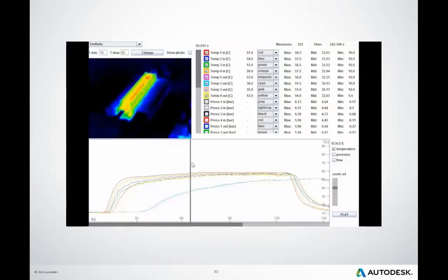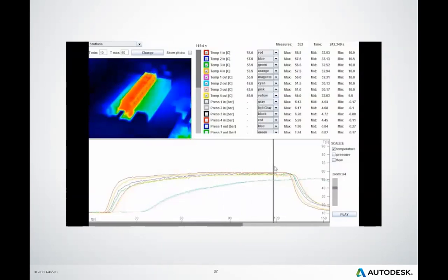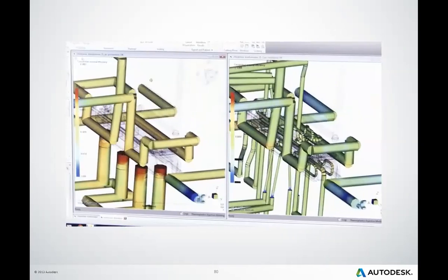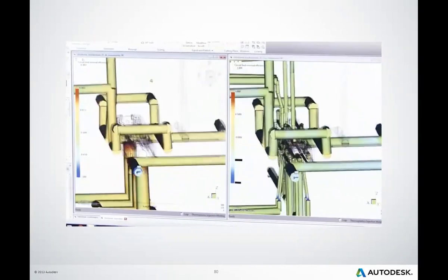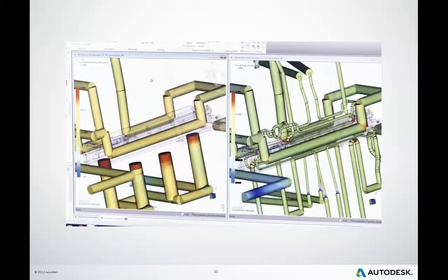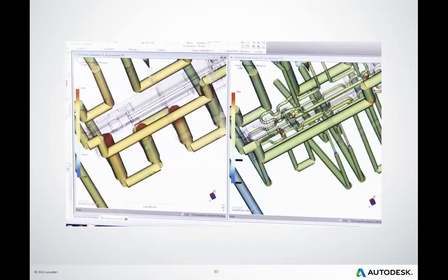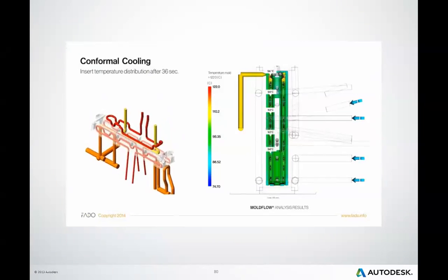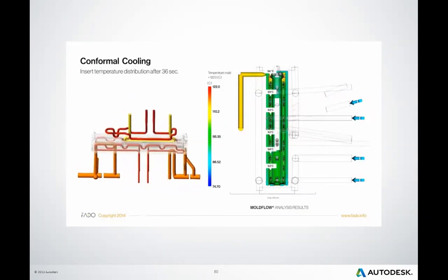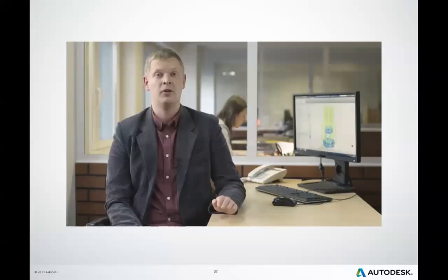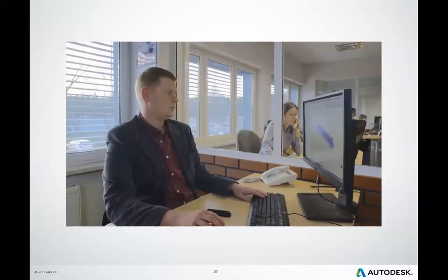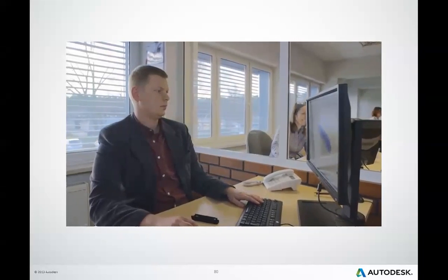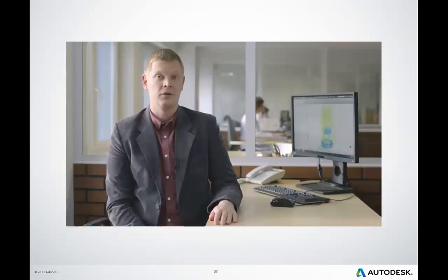In the case of cooling optimization, Moldflow coupled with our thermovision test bench is an important tool for cooling design and verification. Values obtained during simulation serve as a reference point for the thermal behavior of the insert built in DMLS technology. Due to numerous factors influencing the insert quality, such as wall roughness inside the cooling channel, simulation results obtained from Moldflow must always be compared with the actual thermal behavior of the insert, flow rates and pressure losses for individual cooling channels. Only then can we be sure that our cooling design meets our expectations.